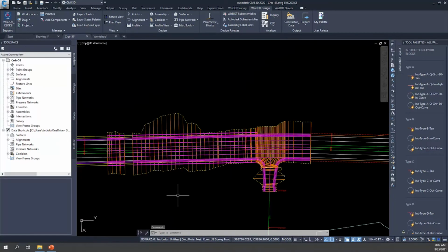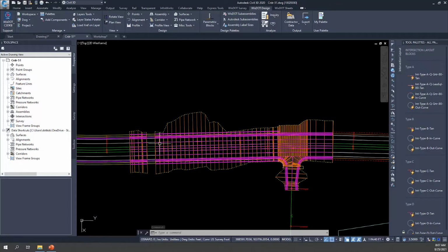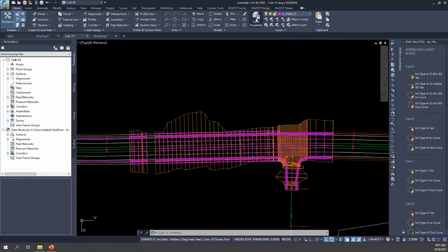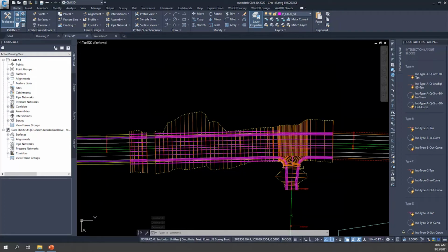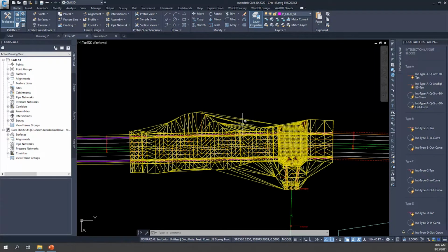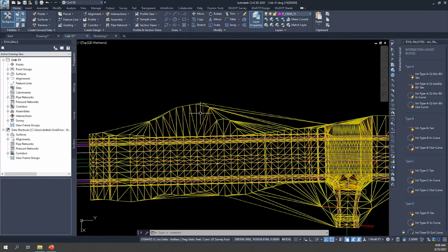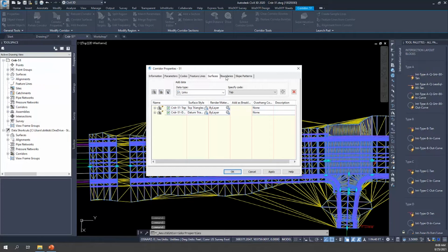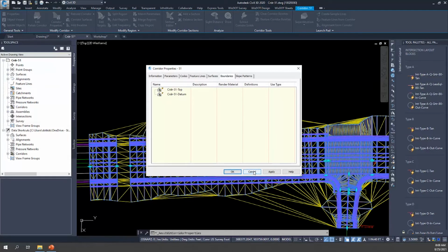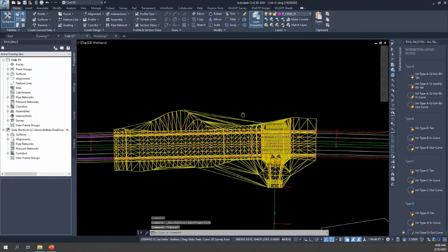All right, so we've got a small little corridor here. I added a gap here just to give you a demonstration of what that gap tolerance is all about. Right now I have my layers turned off. I'm just going to move my layer manager off to the side. So if you see something change, it's just because I turned the layer on and off. So let's start with a corridor top surface. This is right out of the corridor. No boundaries have been attempted here. See, there's no boundaries in here for these corridor surfaces, but we want to create one for the top surface.